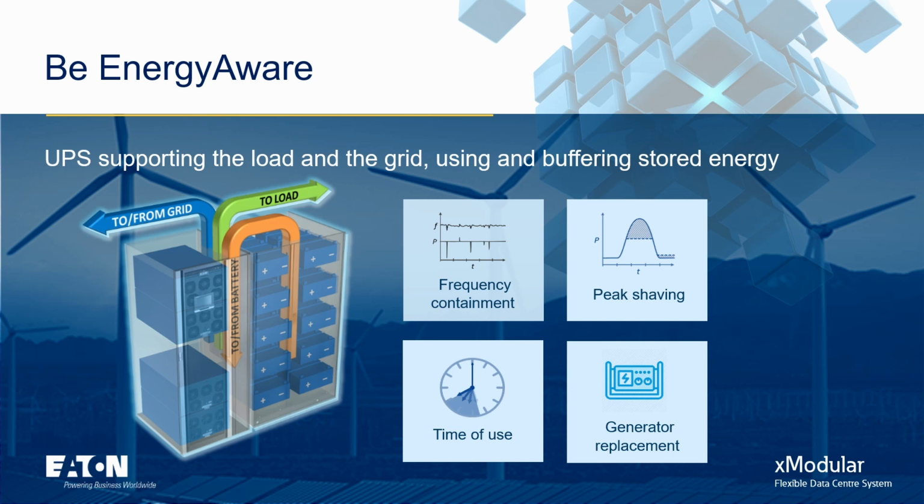These are some of the things that can do. Frequency regulation, peak shaving, and peak shaving is the only one I'm going to cover. Peak shaving is that there's a time where your data center demands more than other times. And we can find ways to make sure that even if your data center demand changes, your electrical demand remains the same.